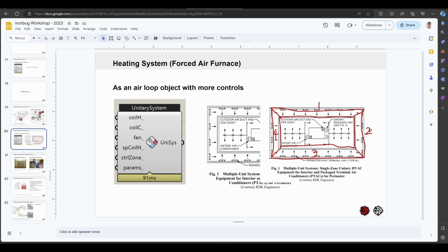And because in reality, for this side, for the west facing thermal zone here, we have 4 outlets, 4 diffusers here. But inside the energy model, we only model 1 zone facing west. We can only have 1 diffuser for this zone. If we want to build something very detailed, if you want to control each terminal individually, then you divide this zone into 4 of them, and then you can assign 4 diffusers to it, and then you have your own logic to control each of them individually.